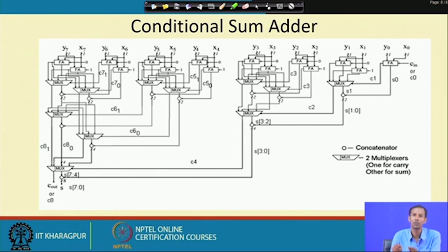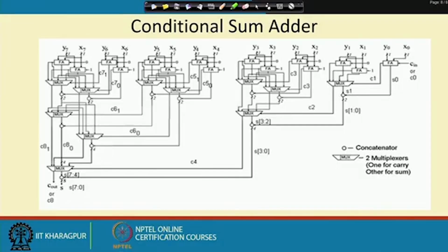The sum and the carry both are affected. So here what are we doing? From the beginning we are calculating the values considering the carry input bit, which is of 1 bit. We are doing binary addition, so it cannot go beyond 0 or 1. That is why we pre-compute these values considering the carry input bit as 0 and 1.